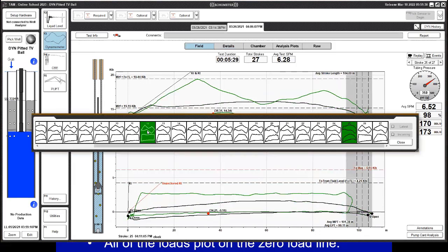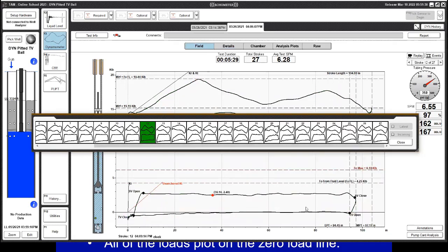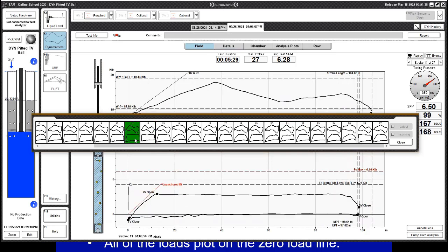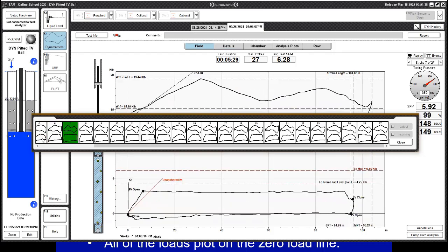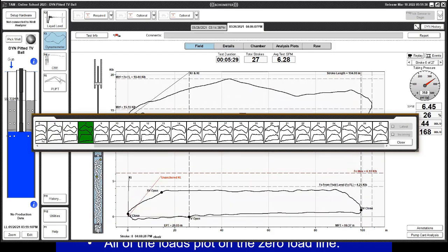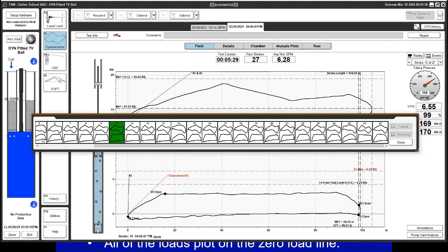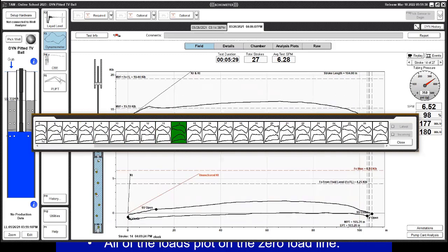By clicking the control key on your keyboard, you can overlay some dyno cards, and you see how this card is more rectangular, looking good, the card shape. This one is not that bad. So we have a changing leakage. Like this is really bad, this is better, this is much better. Some leakage, some leakage. Some of those are like this one, really bad. So on this stroke, the pump didn't produce anything.